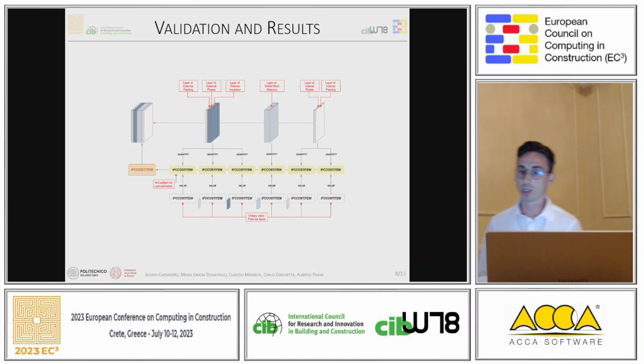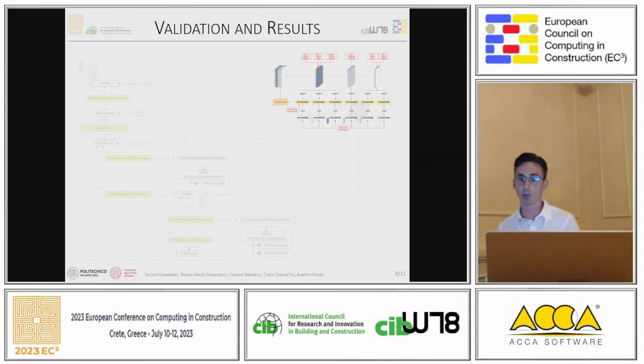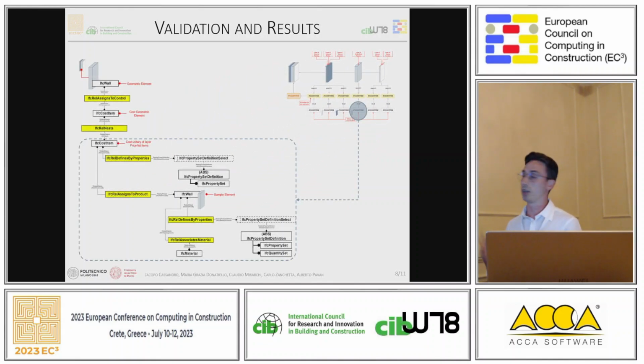At the operational level, considering the design standard, the whole package was divided into 3 different parts, 2 architectural and the structural part, and the price of the 3 parts will be given by the unit price of the price list multiplied by the quantity of the model object. Every unitary IFC cost item contains specific information and data based on the original description given by the price list, and the IFC standard, also through cost classes, offers the possibility of structuring this cost data, creating a cost architecture and not simply an attribute to associate to the BIM object.